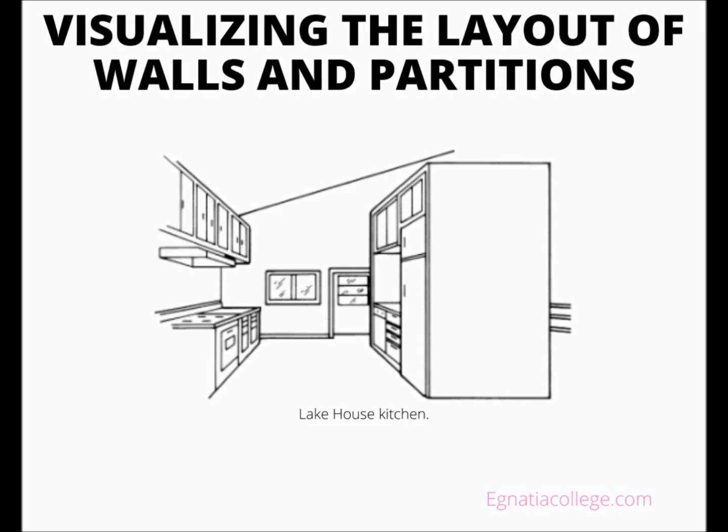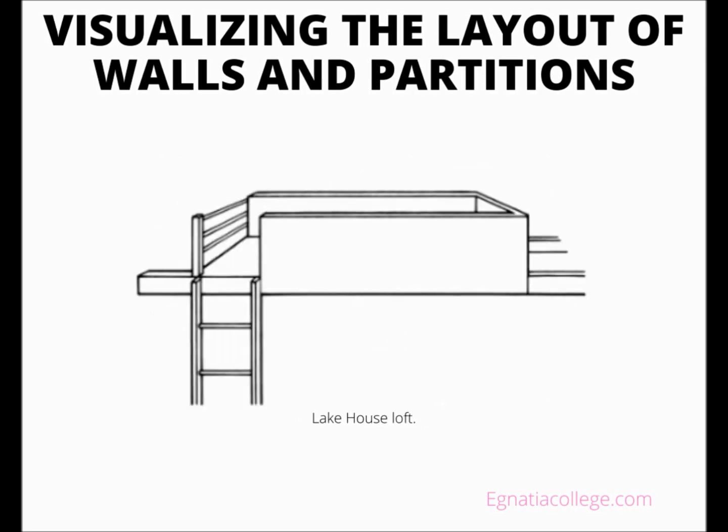Beyond this railing, the floor is open to the playroom below. Above the open area of the playroom is a loft that provides storage or extra sleeping space. Access to the loft is by a ladder in the upper hall. The loft is shown on a separate plan on sheet 4. The loft is suspended on 2 beams of 1 3/4 inch by 9.5 inch LVL. The north and south sides of the loft are enclosed by a wall 2 feet 6 inch high. The east and west ends have a railing.